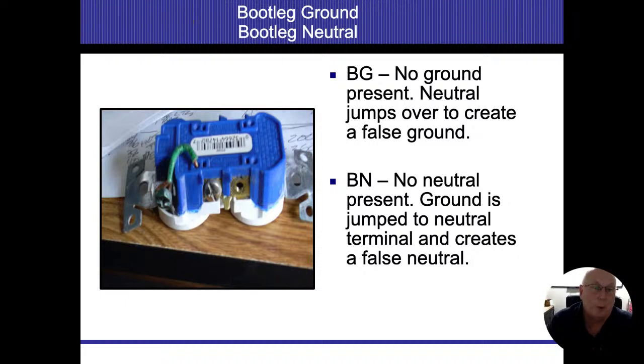This isn't the best practice, and the drawback with this is many of those 3-prong testers we use don't really find it. This gives me one of the cases I make for why I like non-metallic cable. When we're dealing with non-metallic cable, for the most part, they're going to have an energized, a neutral, and also a grounding wire in there as well. So if we end up replacing some of these things, we can still make sure that everything is grounded.